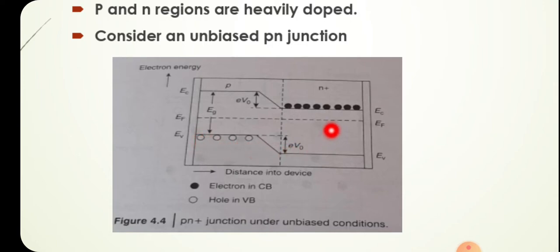This is the basic structure of a PN junction when it is unbiased. Also, you can see that when P and N materials are fused together, there will be an area known as the depletion region, that is a charge free region. The depletion region extends to the P side, and there is an energy difference between the two conduction bands and between the two valence bands. This energy difference is given as eV0, where V0 is the barrier potential or built-in potential.